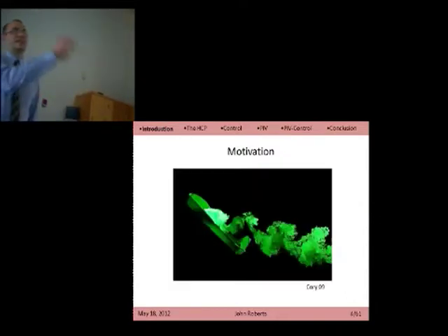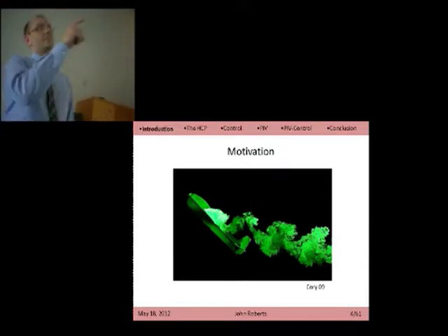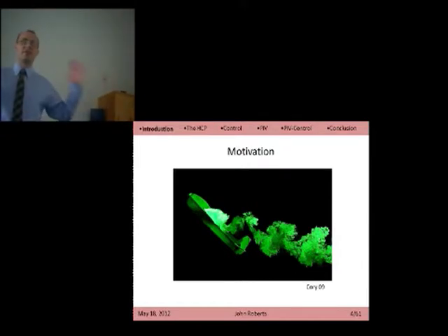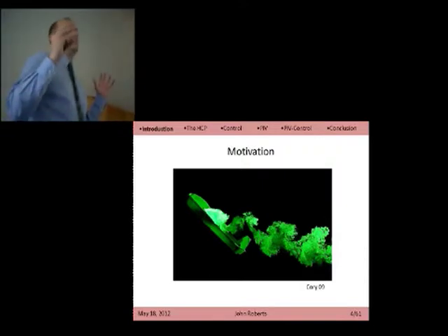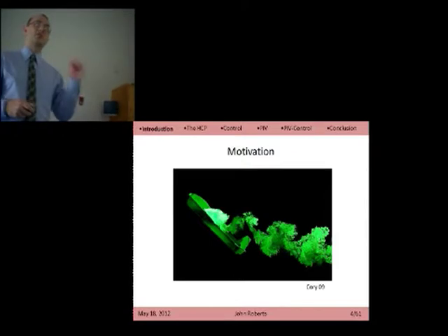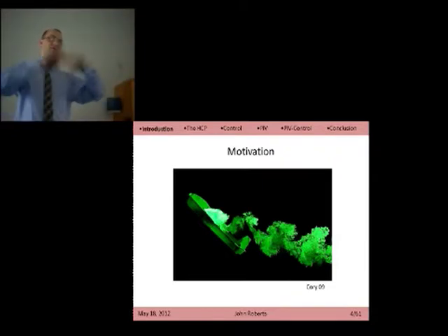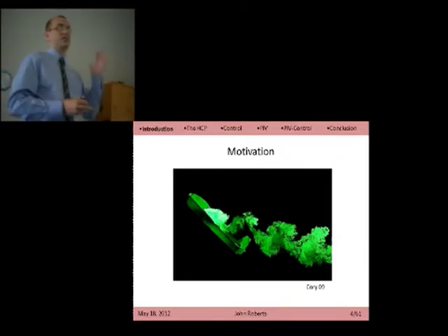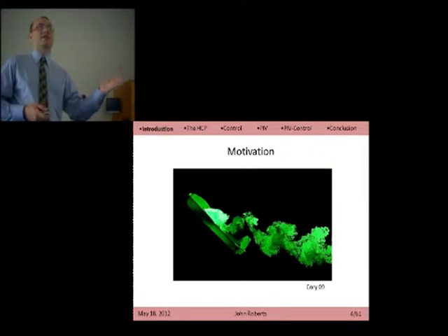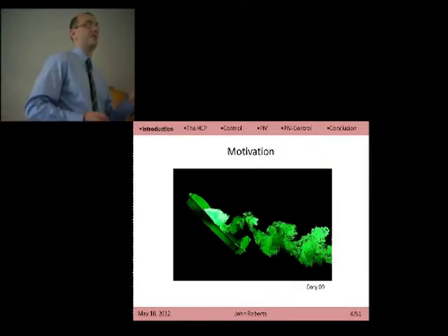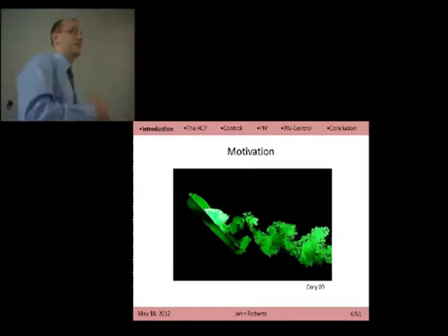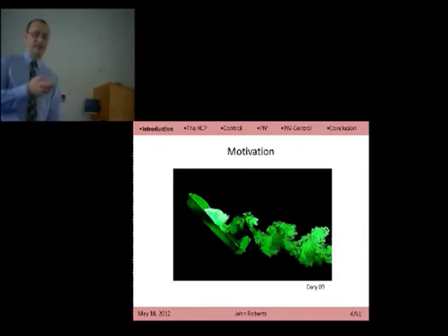When this actually executes this maneuver, you can see here a little flow visualization. The stalled wing has this dramatic periodic wake behind it. The flow is very complicated, difficult to represent. It's transient, and most of all, it is critical to the performance of the task. If we want to slow down quickly enough, if we want to land on this wire, we can't use the normal operating regime of a plane. We have to actually stall the wing, get enough drag to slow down that quickly. So it's critical that we take advantage of the full rich domain of possible fluid dynamics when we're trying to execute these tasks.